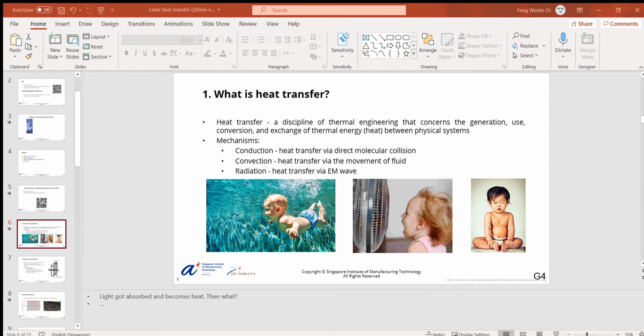All right, I just mentioned a definition known as the thermal conductivity, and it means an object's ability to transfer heat via conduction. In gas, it is through the process of collision of randomly moving molecules. In liquid, it is collision of more closely spaced molecules as well as the molecular forces. And importantly, in solids, it is delivered by the lattice vibration as well as the transport of free electrons.